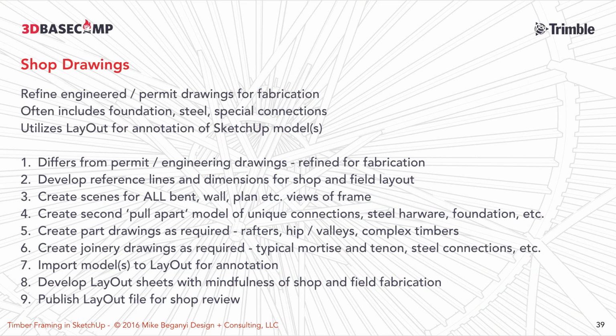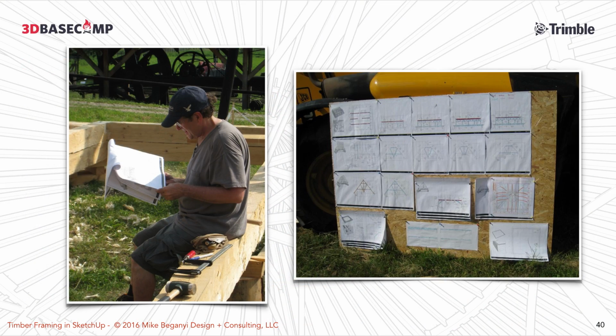A lot of times the dimensions you get on an architectural set are great for figuring out how big the house is and what the floor area is and all that, but it's not really good for laying out trusses or structures or whatever. So I'm mindful of that when I do a set of shop drawings. And then I'll actually try to get the shop to review it before we publish the final set. So, this is what happens.